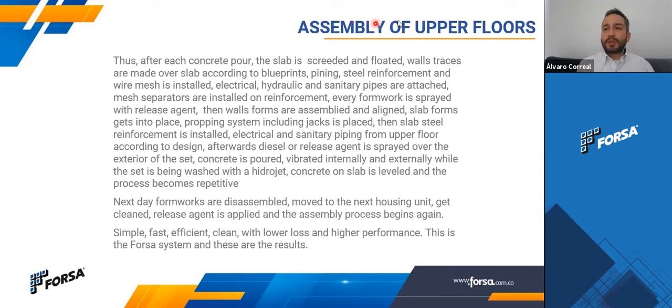If you want to have a special maintenance, it's recommended after each big project. Let's say you build 400 houses, then you do a general maintenance of the forms, and then you start another project of the same kind.